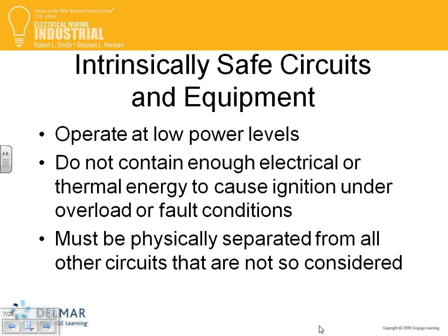The smart guys created a system called the intrinsically safe system. It is a whole system in the code, guys. They make the equipment work at a temperature lower than what can ignite the area. So if there is a gas here that needs 100 degrees Fahrenheit to ignite, and I can bring a fixture whose surface temperature is no more than 50, or 90 degrees Fahrenheit, then I guarantee you it will not ignite the area because it doesn't have enough heat to start the fire. That's basically the intrinsically safe system.